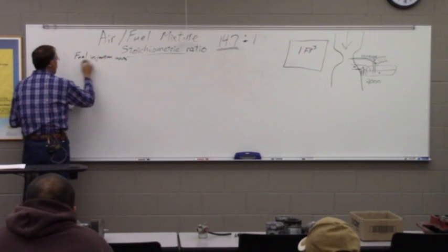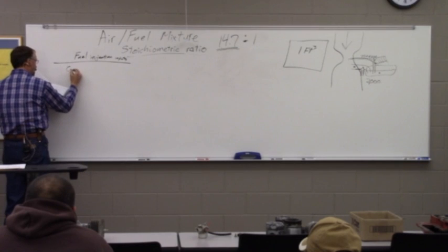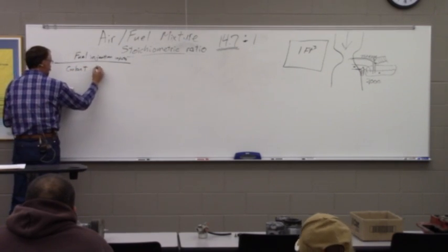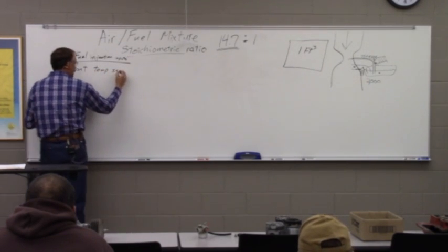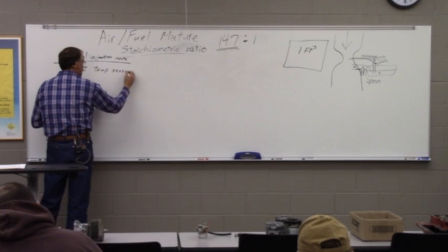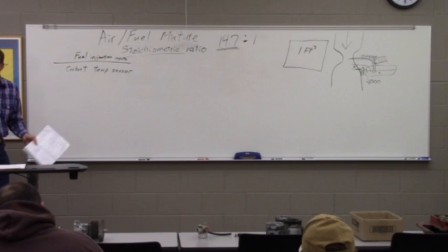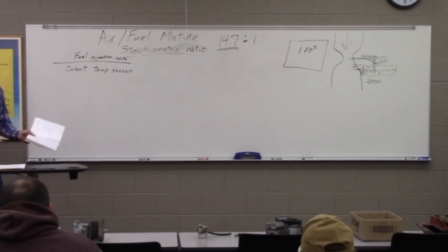So the computer-controlled fuel injection, all of those systems I've ever seen will have a coolant temp sensor, and so what it does is tells you what's the temperature of the water or antifreeze coolant that's in the water jacket on top of the cylinder head and around the cylinders.